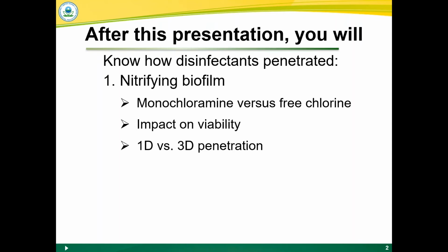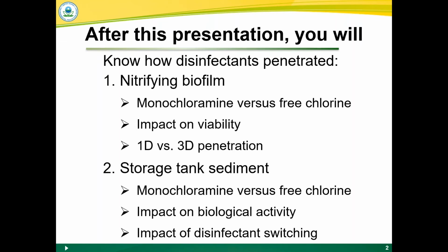And we'll also compare how the disinfectant penetrated that biofilm on a one-dimensional basis and also on a three-dimensional basis to see if there's any impact of heterogeneity of the biofilm. The other main area that I'm going to talk about is storage tank sediments. This is sediment we actually got out of the distribution system. We also repeated some of these experiments looking at, again, monochloramine and free chlorine, how they penetrated storage tank sediment. Also looking at not only viability, but now we're looking at activity.